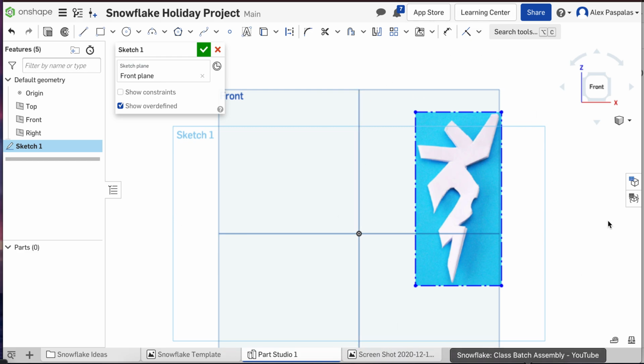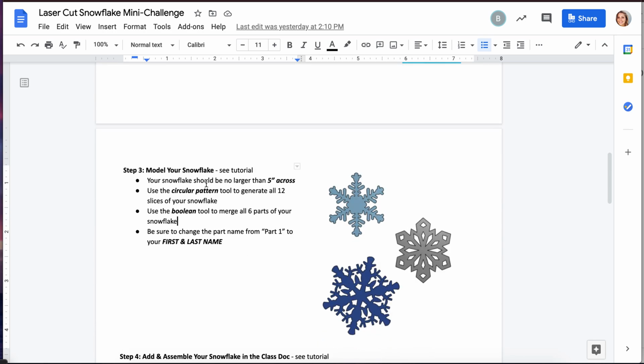Technically, the image you should have taken a picture of is only 1/12 of our snowflake. That's all we're really going to use and trace to generate our entire snowflake. If that's 1/12 of our snowflake, that's 30 degrees out of a 360-degree snowflake. So that's where I'm going to start. I'm going to map out some lines that have a 30-degree angle between them. So I'm clicking the line tool and the construction tool, and I'm going to start creating a vertical line from the origin up.